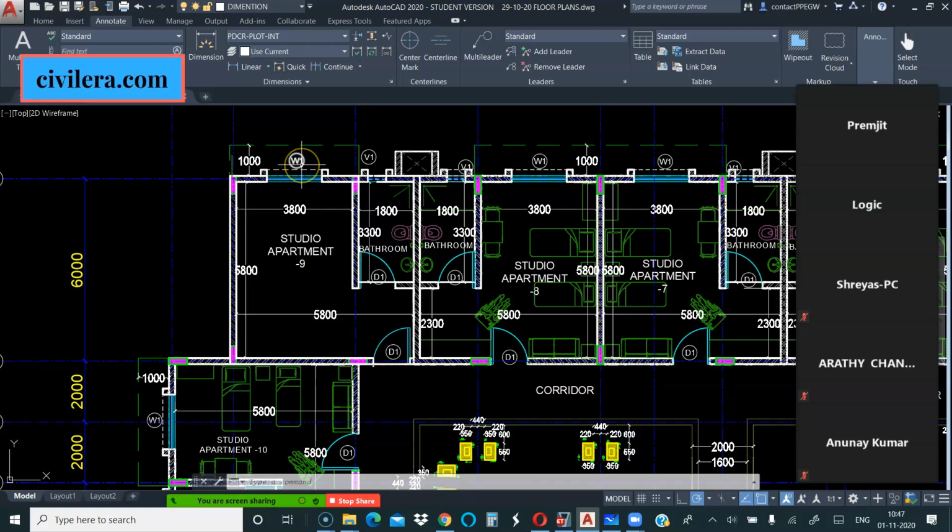It's only a notion that if you avoid soil testing, you can save some 20,000 rupees or 25,000 rupees or whatever. If the project is larger, the cost also will be larger. Client will think like that. Sometimes even architects will think like that. But the fact is that if your SBC that you get is more than what we assume in the absence of a soil report, the saving that you can make in size of the footing is much higher than what you think you can save.